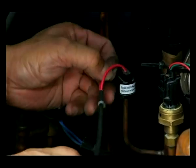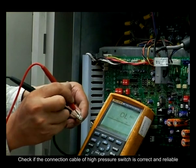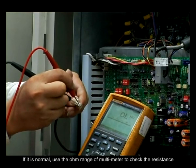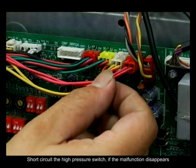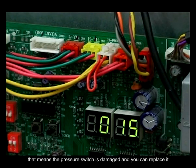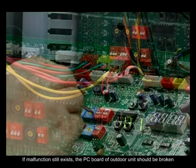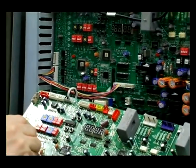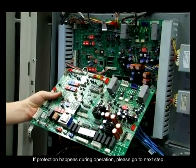Step 1. Check if the connection cable of high-pressure switch is correct and reliable. If it is normal, use the OHM range of multimeter to check the resistance. If it is open or infinite, that means the sensor is broken. Short circuit the high pressure switch. If the malfunction disappears, that means the pressure switch is damaged and you can replace it. If malfunction still exists, the PC board of outdoor unit should be broken. You have to replace a new one. If protection happens during operation, please go to next step.